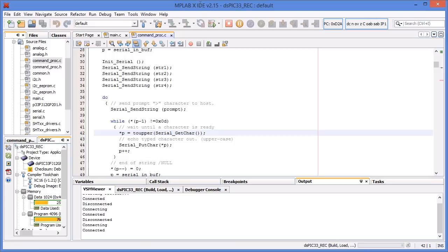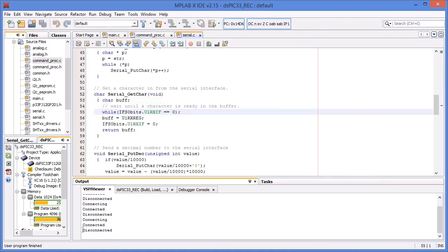At the end of the debug session, you can end the simulation from the control bar in MPlab. After closing the session, a final message is displayed in the VSM Viewer tab to tell you that MPlab has released Proteus and the two programs are no longer linked.